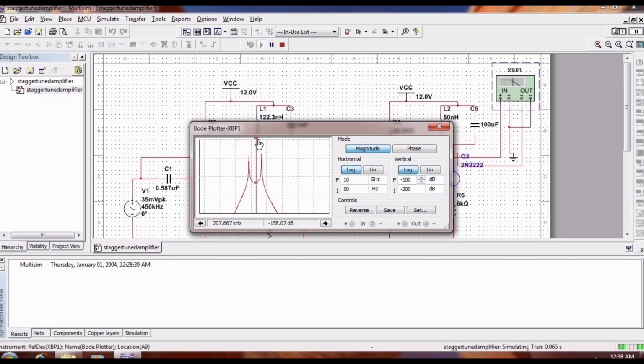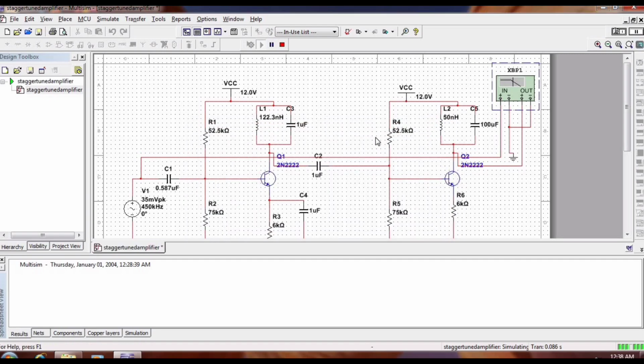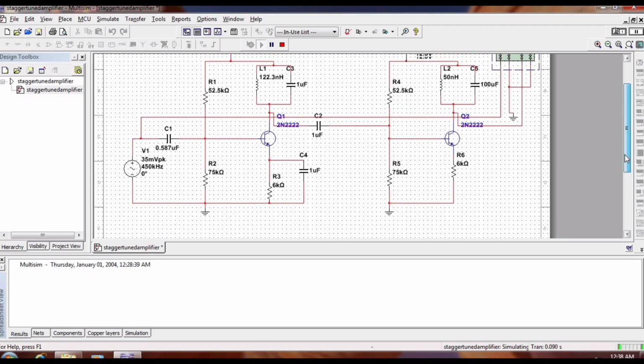So, from the above information, finally, we can conclude that these amplifiers are usually designed so that the total frequency response exhibits the maximum flatness, approximately at the middle frequency. It requires several tuned circuits to operate in combination. Once the frequency is changed above and below, the resonance frequency will fall off quickly. So that is what we see in the output.